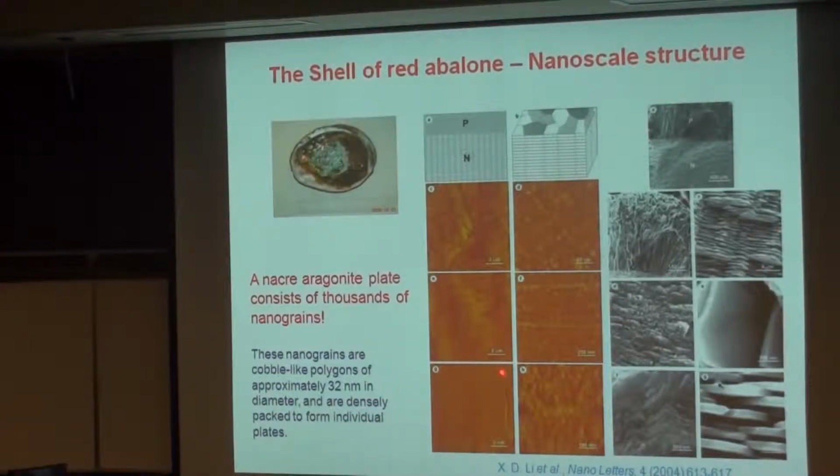So my student looked at this tile, brick from the top view, and then zoomed in, blew it up. You can see 30 nanometer nanoparticles. And from the fracture surface, you see this is the brick surface, there are a lot of surface nanoasperities, like Xiaodong discovered. Those surface nanoasperities can work as interlocks against neighboring bricks sliding, contributing significantly to the strength increase and in particular toughness increase.